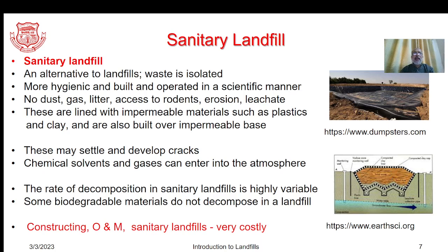It is more hygienic and built as well as operated in a very scientific manner, and hence we concentrate on certain concepts such that there won't be emission of dust, gas, litter, nor will it be open to rodents, and there won't be much erosion or production of leachate. Hence we induce inherent components like liners, which are impermeable layers created using plastic as well as clay, and this is also based on an impermeable base.